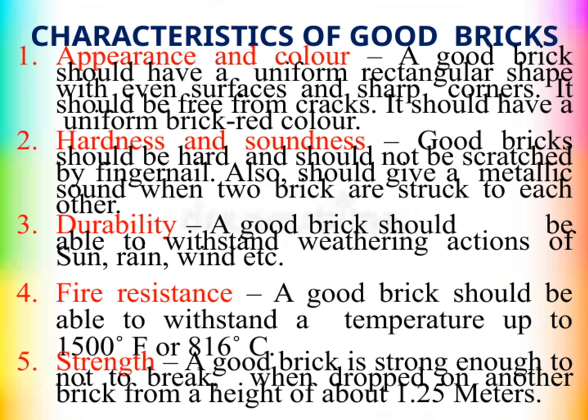Next, let's talk about hardness and soundness. A quality brick should feel hard to the touch. It shouldn't scratch easily with your fingernail. When you tap two bricks together, they should produce a clear, metallic sound, which signifies good soundness and that the brick is solid and well-made.